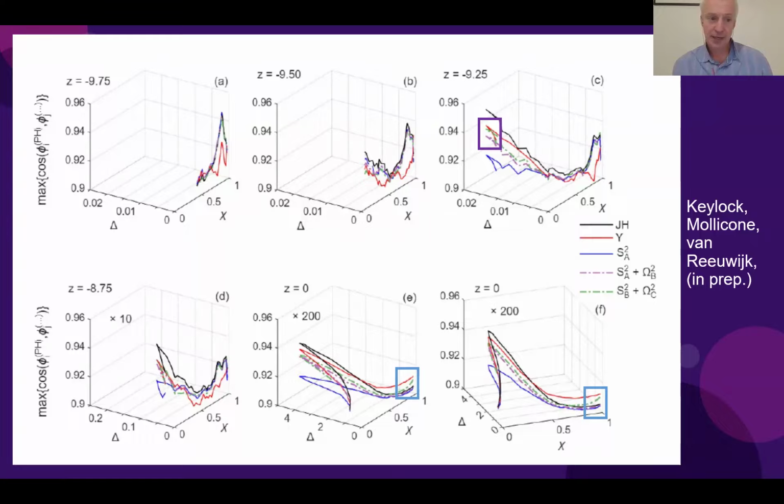You see, we start off, delta is based in top left, delta is very close to 0. We don't have, on average, much coherent motion. We're right on that edge of the jet. Chi is typically strongly positive, which means a dominance from the deviatoric part of the pressure Hessian, or C, in our terminology. And you'll see, first of all, that the Zhang and Hossein approach has a strong maximum at this 0 for delta, close to 1 for chi.